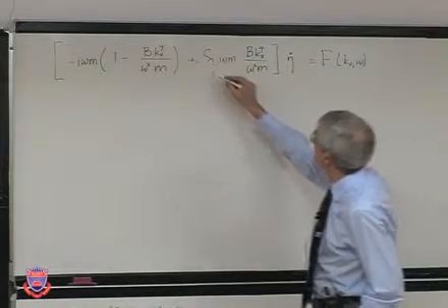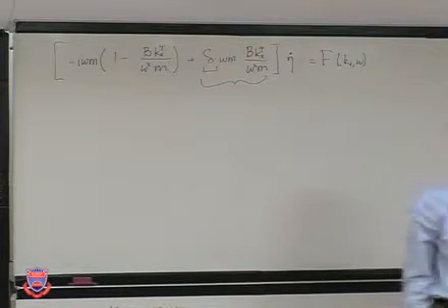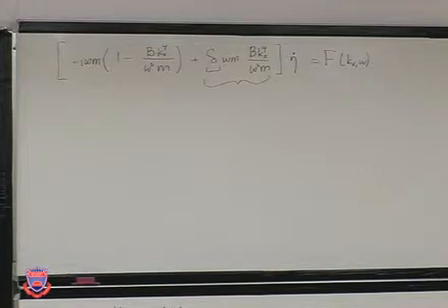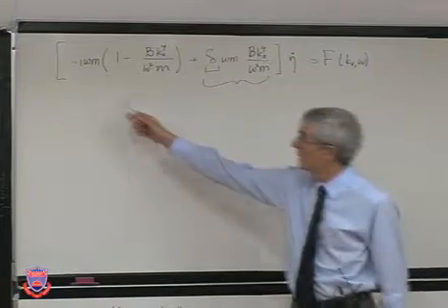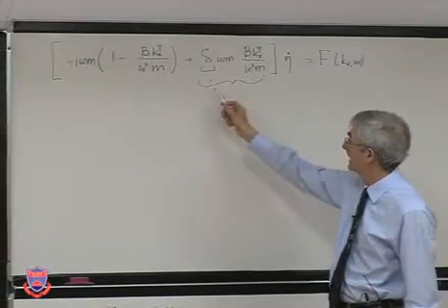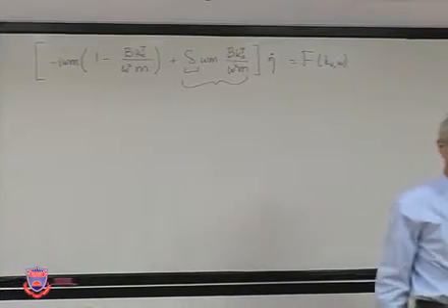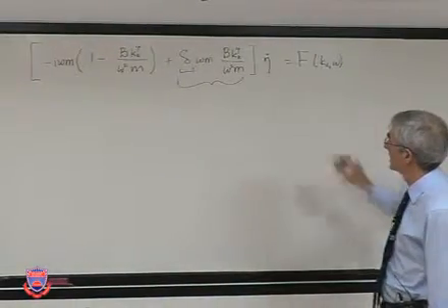What you see now is an additional term in the impedance. If you go back and look at the ordinary single degree of freedom system vibration equation, you'll see something very similar to this. Okay? The resonance part and the damping part. If you look at the impedance expression for a single degree of freedom oscillator, you'll see a similar expression.